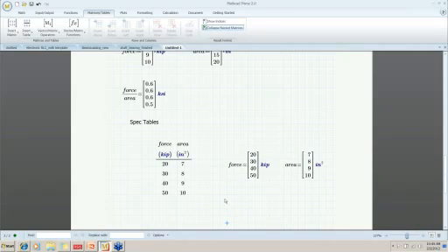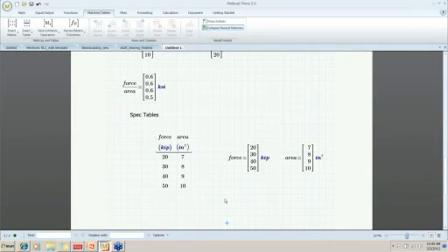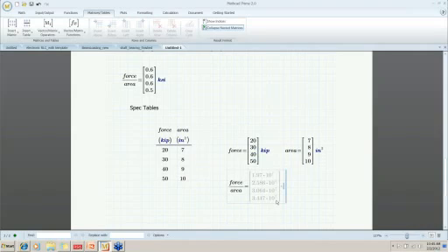And now we can divide those by each other. Force divided by area, just as we did before. We don't like pascals, we want KSI. Or we could even write kips per square inch if we want to spell it out. And now here we can assign this to a variable, capital P, or pressure. Now we can use that pressure going forward in the next calculation.